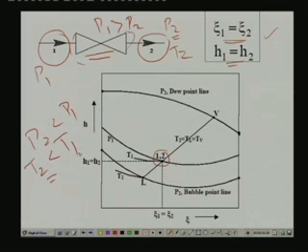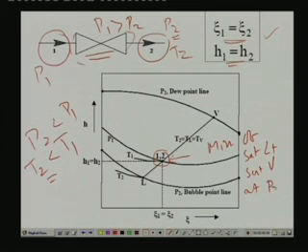Okay. So, how do we find these outlet and inlet pressures? We know that this exit condition, for example point 2, is a mixture of saturated liquid plus saturated vapor at outlet pressure P2. That means suppose this is the saturated liquid condition and this is the saturated vapor condition at the outlet pressure P2, and if you know these, then by trial and error method you can find out the temperature. Because this temperature is nothing but the temperature of this isotherm. So, this is how we have to find the exit condition of the throttling process.